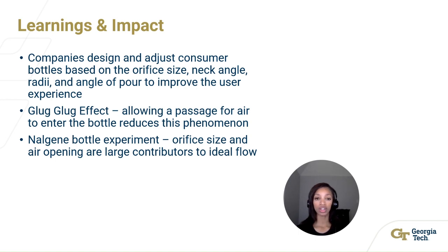In the previous slides, Lauren touched on the findings of the experiment with the Nalgene bottle, but in summary, we discovered that the orifice size and having an air opening plays a huge part in optimizing the flow out of the bottle. We believe that the experiment was effective. However, for even further learning, the scope of the experiment could have been extended to test a different container or a fluid with a different viscosity. Regardless, though, our learnings are applicable to consumer product design as a whole, and it really helped us to understand what must be thought of in designing such bottles.